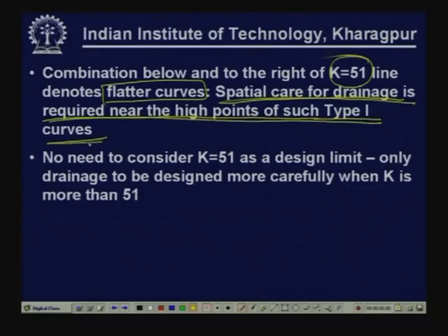However, this k equal to 51 should not be used as a design limit. What we are trying to indicate is that if the k value is more than 51, special attention is required for drainage, but it is not that k more than 51 is not acceptable.